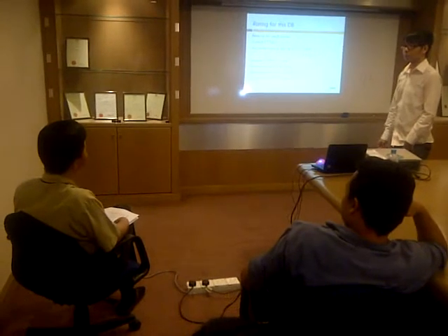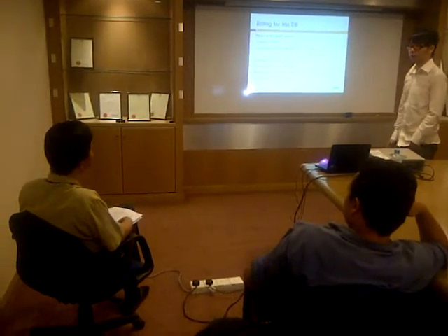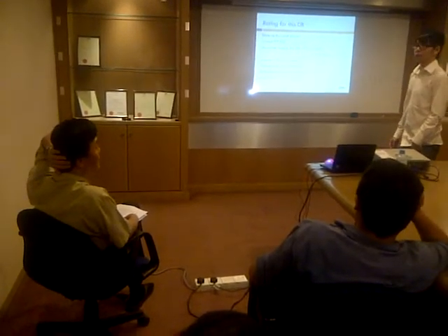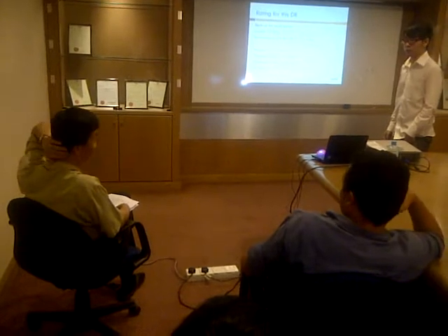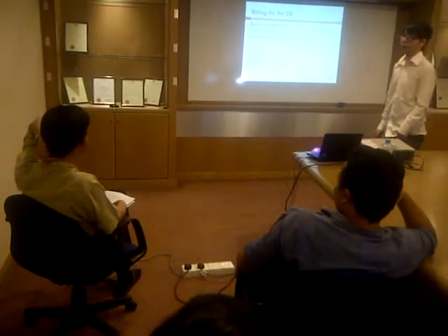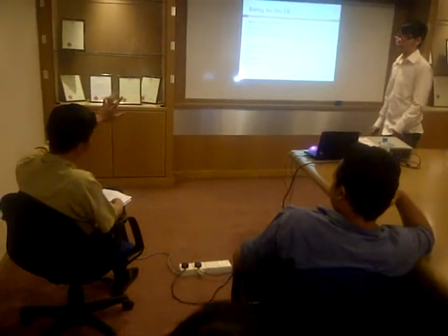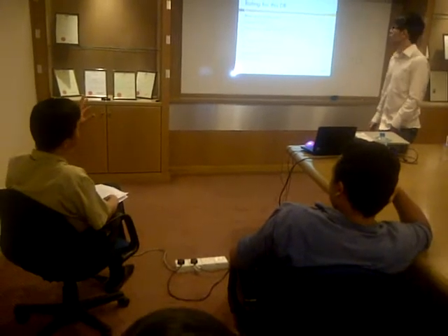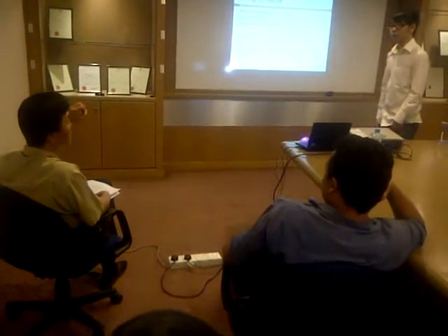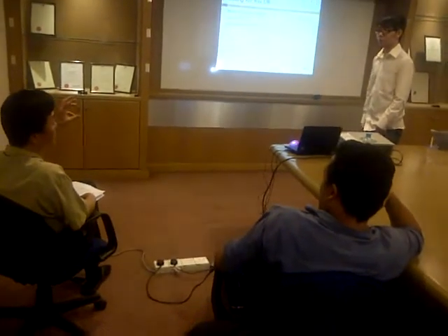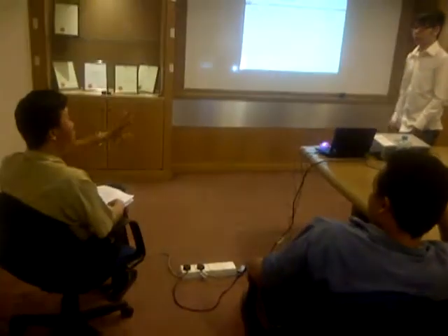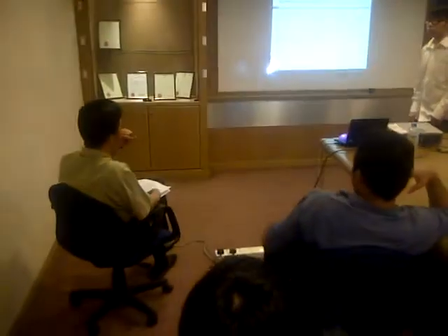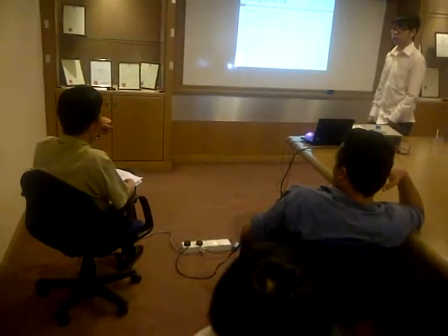Okay. So your assumption for socket outlet is how many watt per socket outlet? Per socket outlet 1,500 watt. Too high. Generally, in industry practice, 250 watt per socket outlet. Computer actually, when you plug into a PC, how many watt is the switch plus monitor? Let's say I do assume laptop, 500 watt. Maybe even higher. 500 watt. Okay.